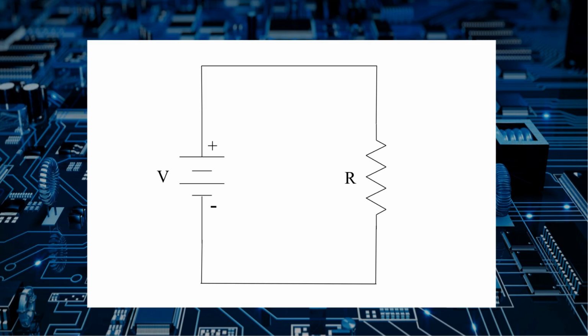Let's start by drawing a simple schematic diagram of a resistor circuit. The standard schematic symbol for a resistor, the American standard anyway, is shown on the right of the circuit and labeled R. The symbol can be drawn vertically, horizontally, or even at an angle, although we usually avoid drawing components at an angle unless we're looking at a specific configuration, such as a delta or a Y. Also recall, a resistor has no polarity and can be drawn either way round.